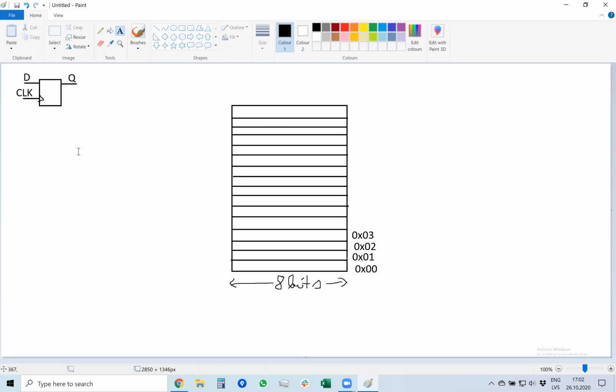So some clock signal. And then, since we have many locations, we also need to control which memory location is updated and which memory locations are not touched. For example, if you want to select only a certain memory location for update, we also need some kind of control signal, which we will call write enable.